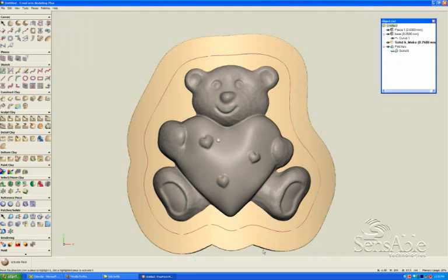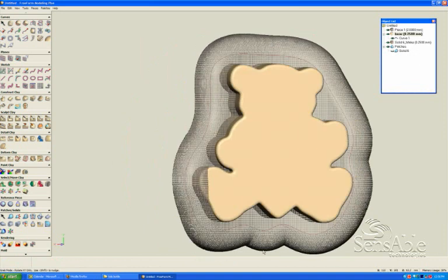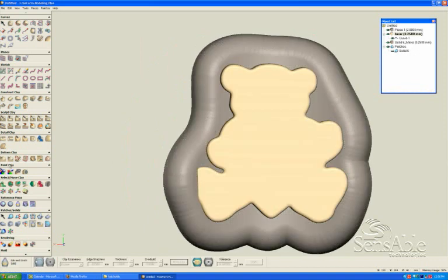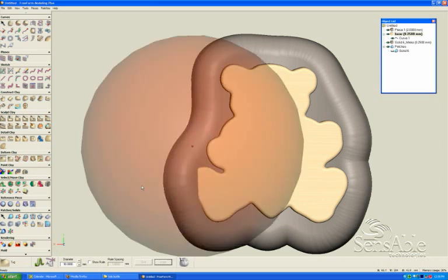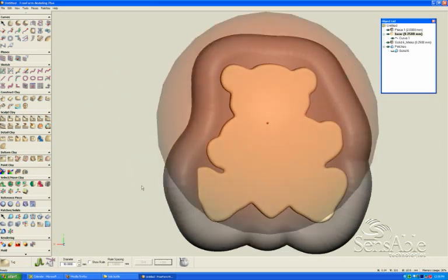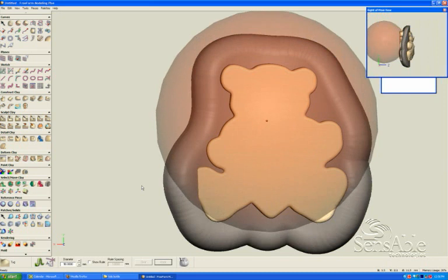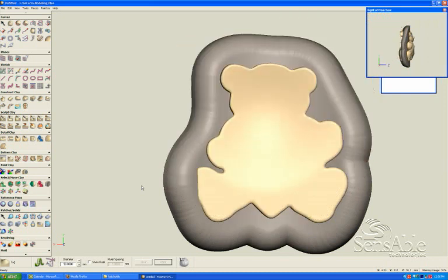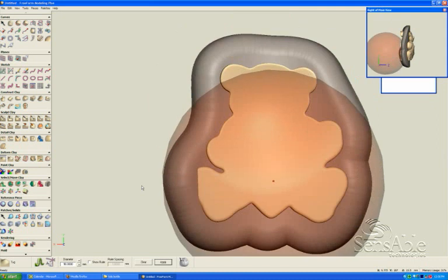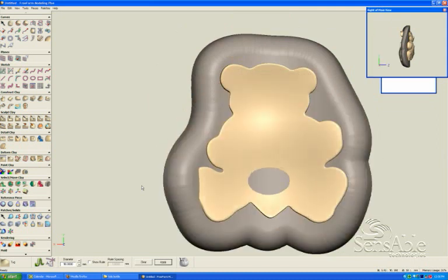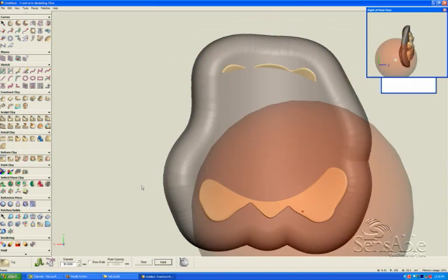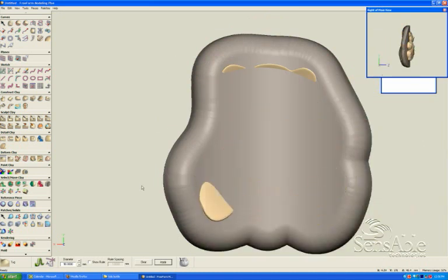The reason we've thickened it with an overbuild is so that we have a substantial amount of geometry with an overlap, so that when we create a surface, we have some overlap to trim and then stitch the surfaces into the model of the baby's bottle. Right now I'm using my tug tool to push some of the overlapping geometry that we don't need into the thickened part, so that we don't have any excess data on the back side.